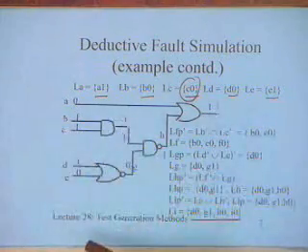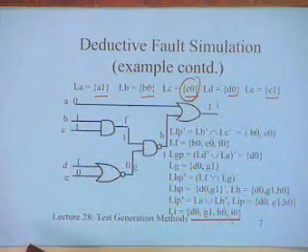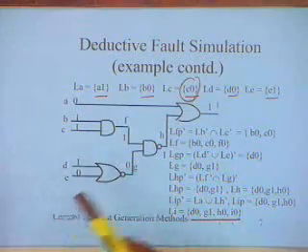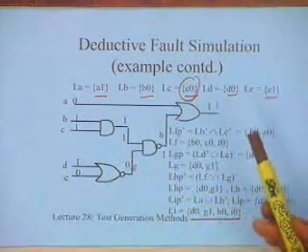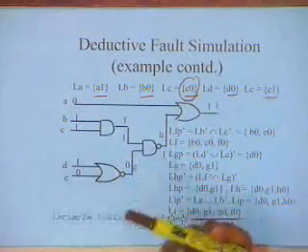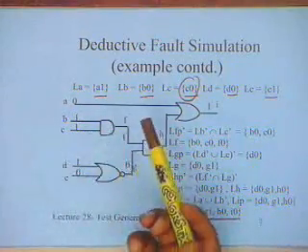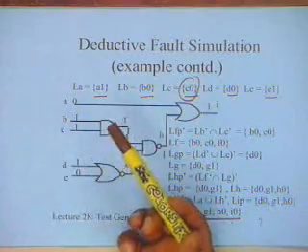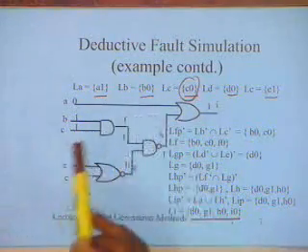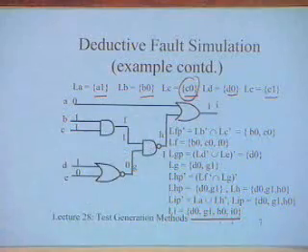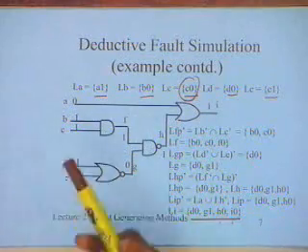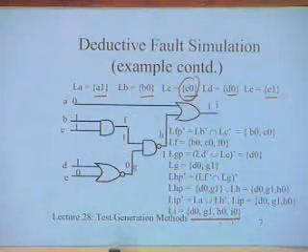I have to of course consider other test vectors, and I have to consider test vectors which are complementary, in the sense that they detect faults which are not detected by the ones already included in your test pattern. Those test vectors may be detecting fewer faults, but they detect faults not covered by the other test vectors, so they are preferable, so that I can build a set of such test vectors.